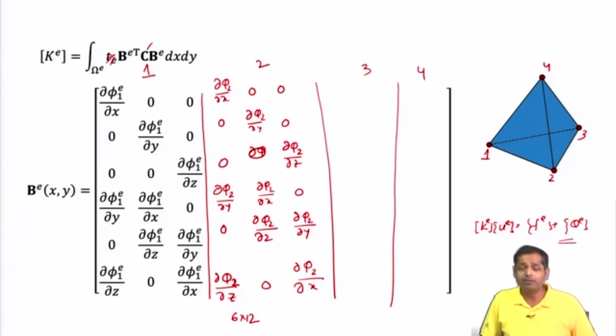In the finite element method, we discretize the entire domain into a collection of elements, but in the element free method, there are no elements. The entire system is discretized by a set of points, a set of nodes. So from the finite element discretization, if you remove the elements, you are left with a set of points. That is the discretization used in the element free method, also known as the particle based method.